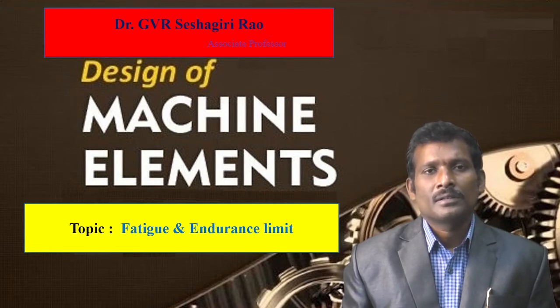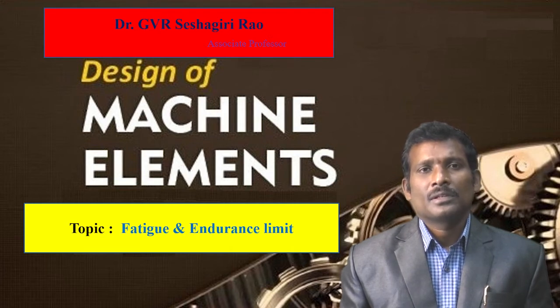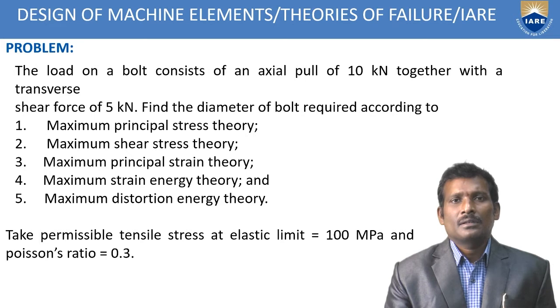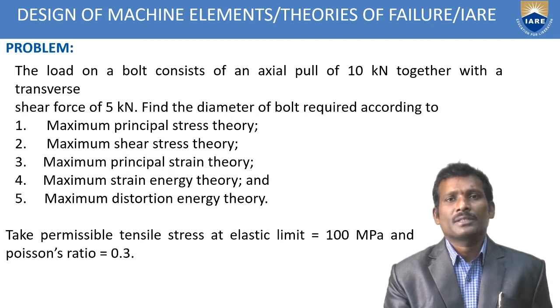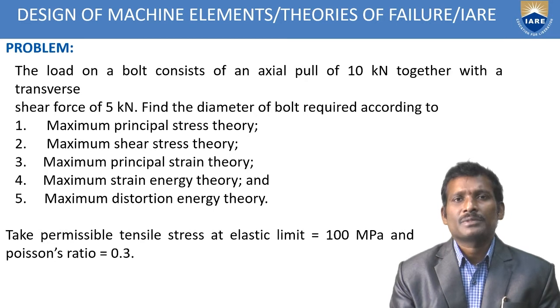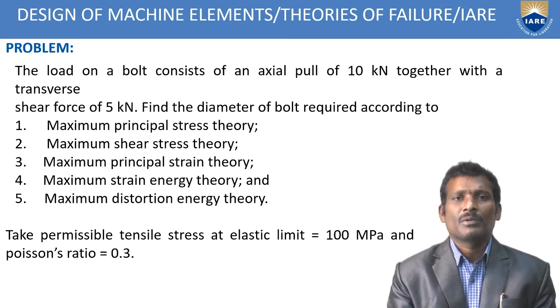In this session, I would like to discuss theories of failures problem solving, that is, how to apply different theories to problems. In previous sessions, we have already studied theories of failures. There are 5 theories: maximum principal stress theory, maximum shear stress theory, maximum principal strain theory, maximum strain energy theory, and maximum distortion energy theory.